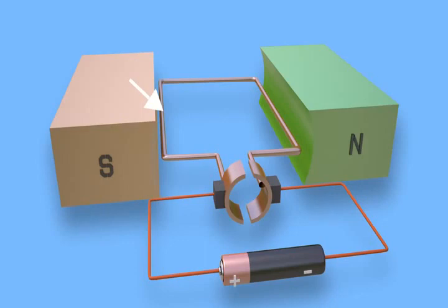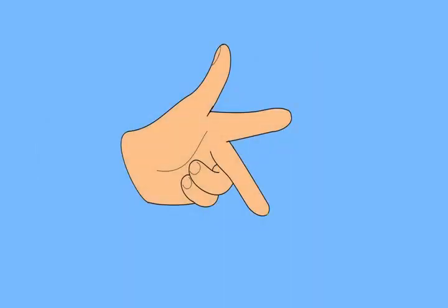The position of the conductors has changed here. That means the conductor which was previously in the left position comes to the right position, and the one which was previously in the right position comes to the left position. At that position, we can determine the mechanical force by applying Fleming's left-hand rule. Let's do that.